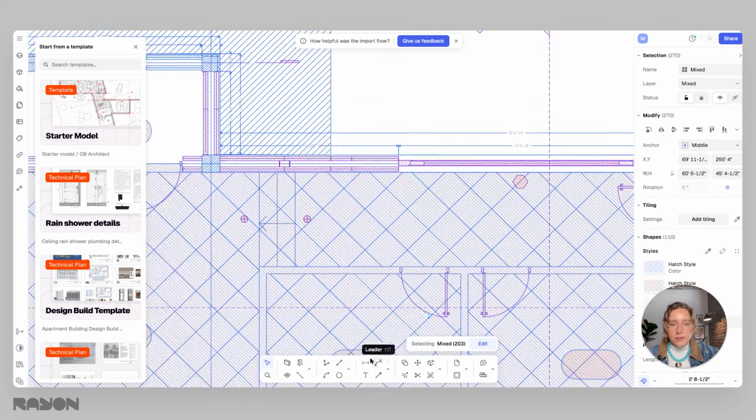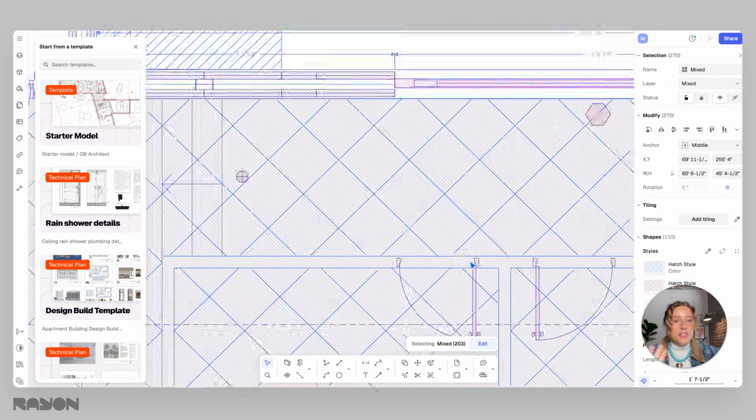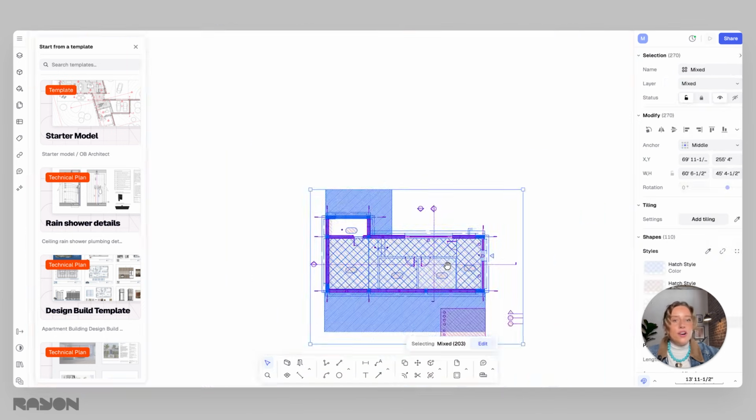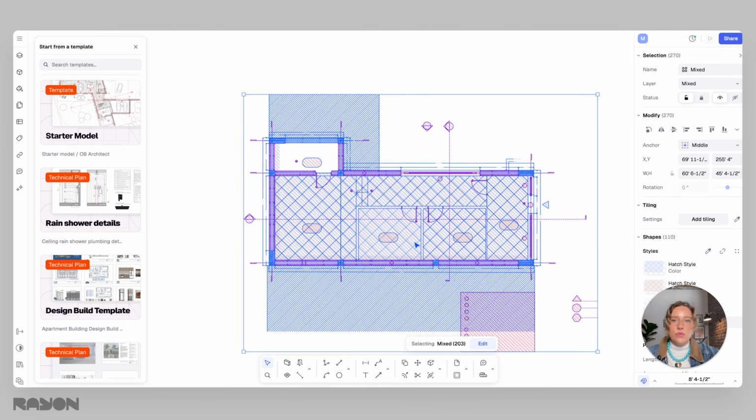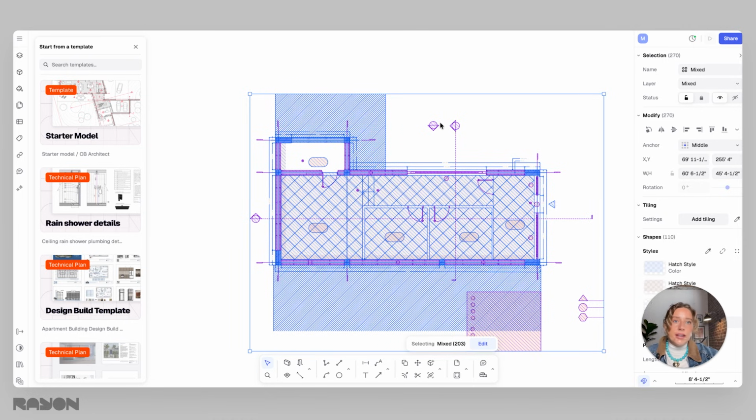And then if I take my dimension tool and dimension that opening that we just looked at, 2 feet 5 inches, that's 3/4 of a meter. So that is correct. I just like to double check that real quick before I start drawing because we want to make sure that everything is to scale. In this example today, I'm going to be showing this small cafe design project where we're just going to test fit a few different staircase types to see what is the most space efficient option.